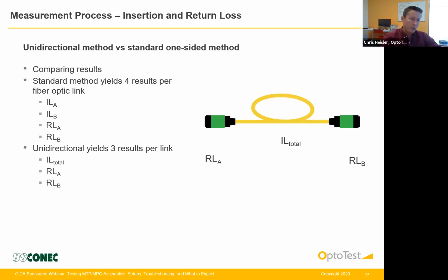The launch cord is connected to the equipment cable, and the open connector on the launch cord will be your reference connector. So yes, in effect, they are interchangeable. You're using the reference connector on your launch cord to perform your measurements, so you could also call it a reference cable.